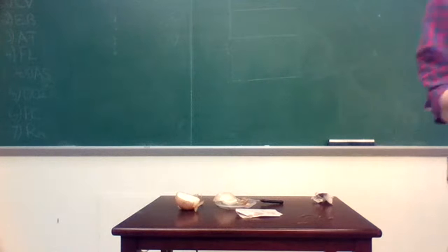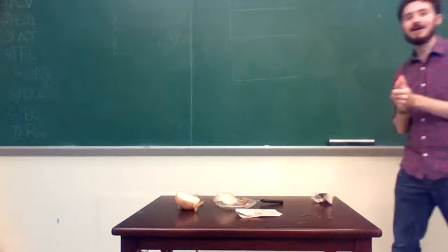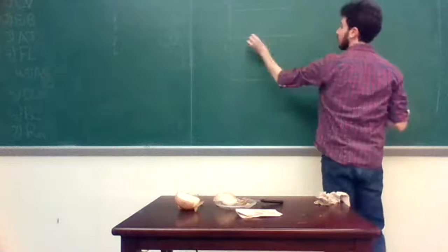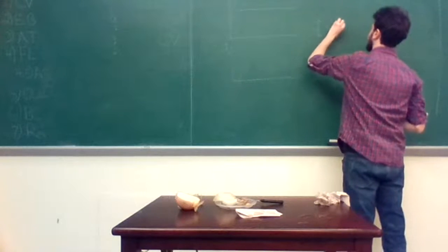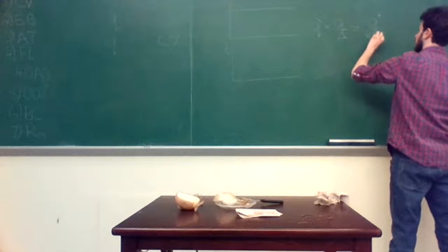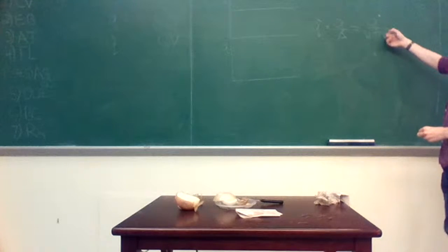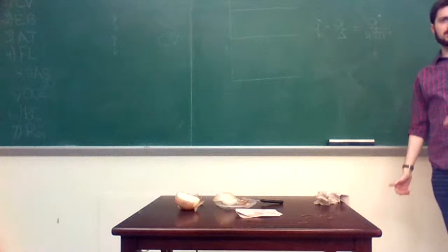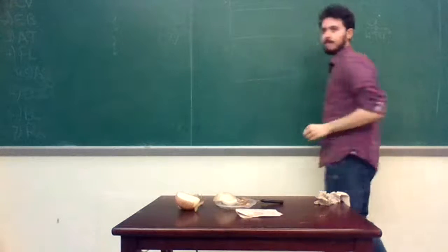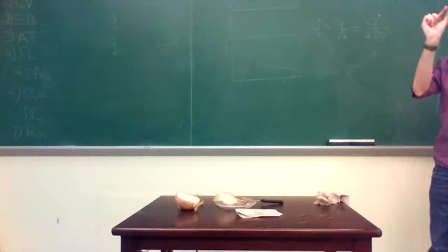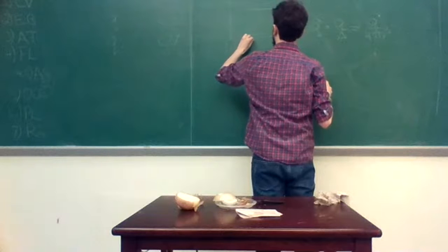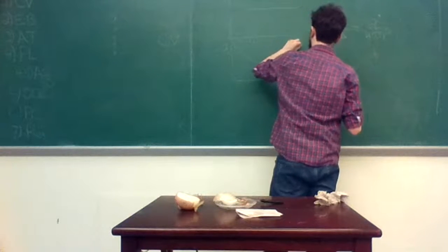All right. Okay. That was the whole point of this onion exercise. So basically, Q is constant, but Q double dash, which equals Q over A, which for the sphere is Q over 4 pi r squared, right? That's the surface area of the sphere, so it is going to decrease with 1 over r squared, which looks like this, I think. And as you go all the way to the center, your area goes to 0. Well, actually, I guess you never get all the way to the center, because the thing's only defined between R inner and R outer.